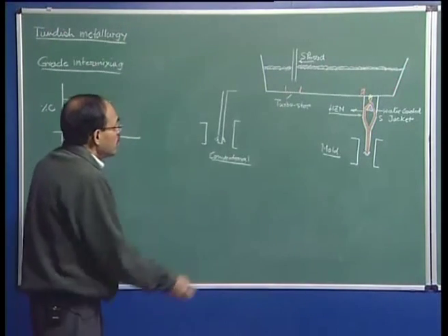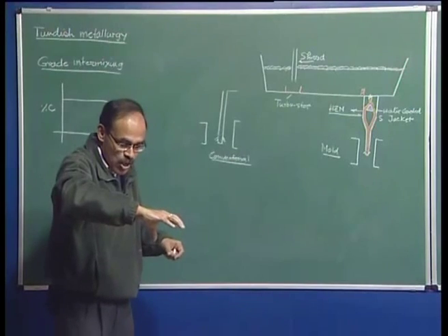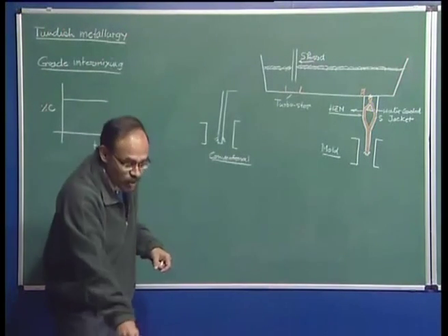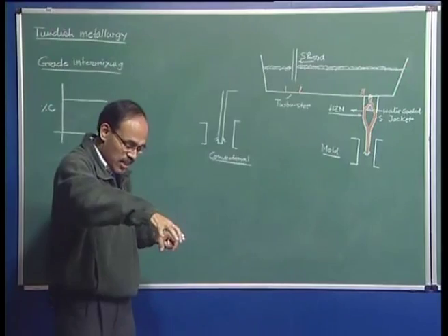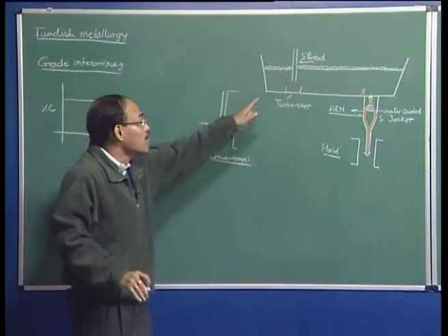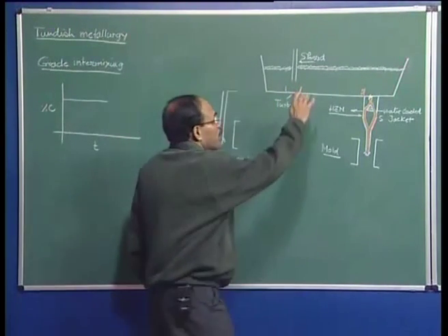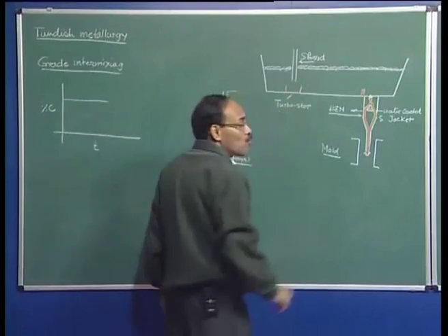Now, when you withdraw this ladle, for this particular time there is no material flowing into the tundish, so the tundish is exhausted and the turret undergoes rotation like this. For some time no material is coming into the tundish, as a result of which the bath of the tundish is going to go down.